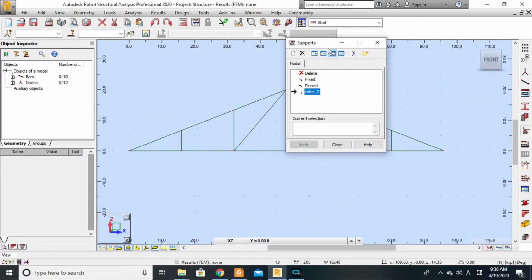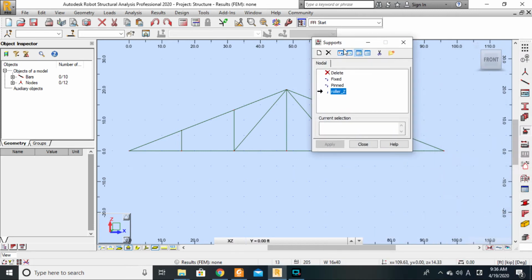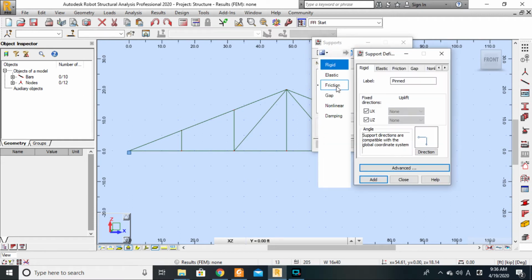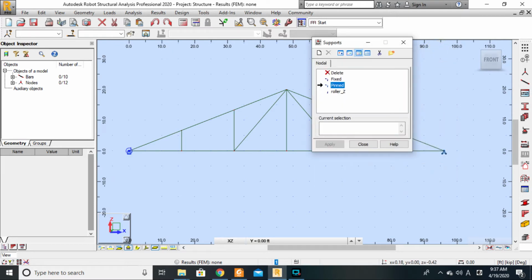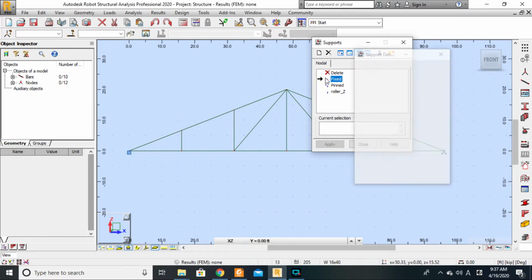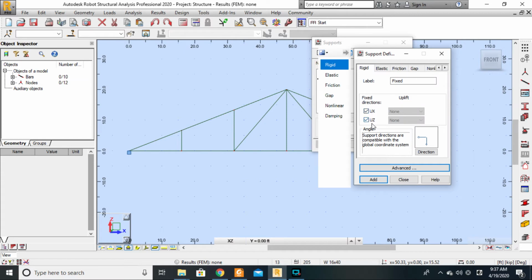We'll just click right here, and the roller support, we said it is on this node, so we'll click on that, node 7, and then the pin support is on this other node. We'll click on that, node 1. Okay, I hope that's a pin support. Why is it modeled as a fixed support? Let's look at its definition very well. Okay, UX, UY, sure. Okay, just to be sure. So that's a pin support. Let's be sure about the difference here. We have UX, UY, the same thing.